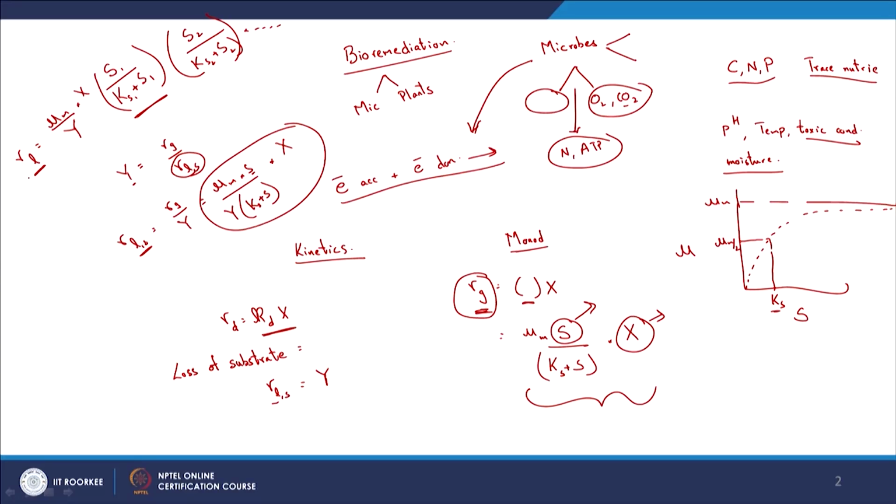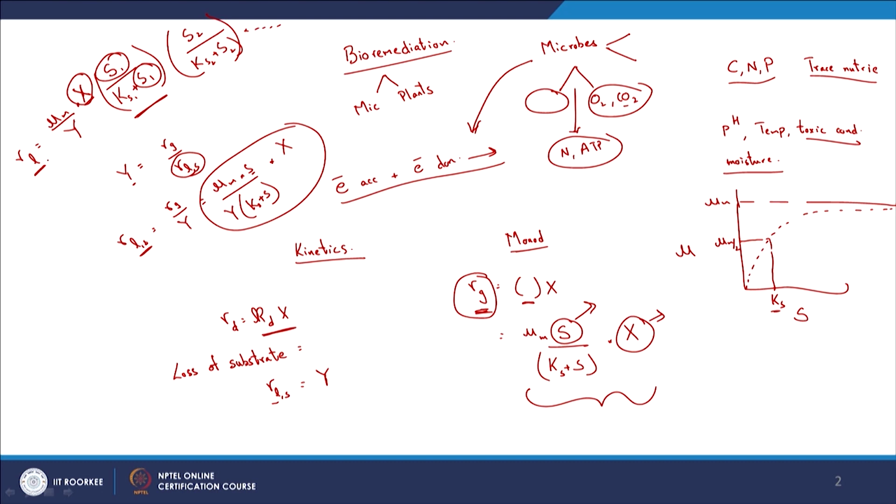Typically, you might have seen this equation in wastewater, in cases where you are looking at the degradation of wastewater, and people might have looked at only one limiting substrate. So again, the rate of loss of the relevant contaminant obviously depends upon the concentration, and of the microbes, and also the concentration of electron acceptors, donors, or other limiting substrates. That is something to keep in mind. Again, X is the concentration of microbes. As you can see from this equation, the greater the concentration of the relevant microbes, typically the better the performance, or the faster the degradation of the relevant contaminant.